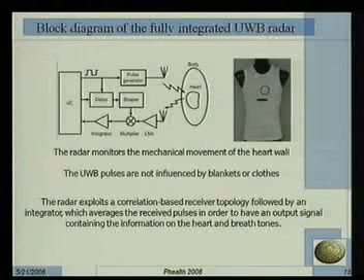By modifying the delay, we can optimize the output of the multiplier, and then the output of the integrator. The integrator is very important in order to bring the signals to baseband, in order to be processed, in order to detect information about the motion of the heart wall.